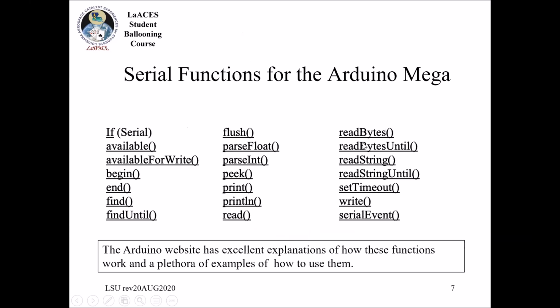Okay, so again, the Arduino is really nice because it has these great built-in functions for you, so you don't have to worry so much about the details of what you're sending across, or all of the underlying things that need to go on in order to send serial data. All you have to do is set up the serial port, connect the wires, and then you're able to use these commands where you can read a byte off of the serial port, or write if you want to write something.